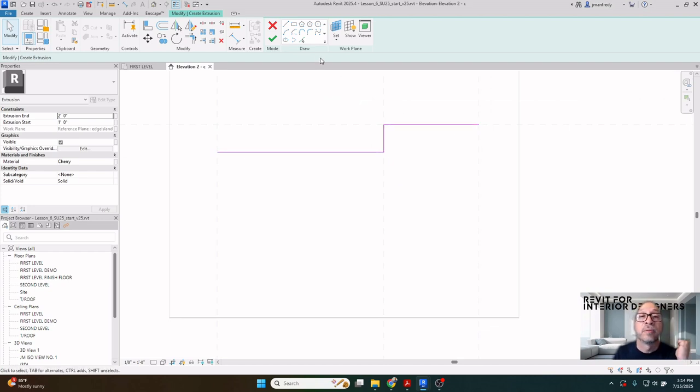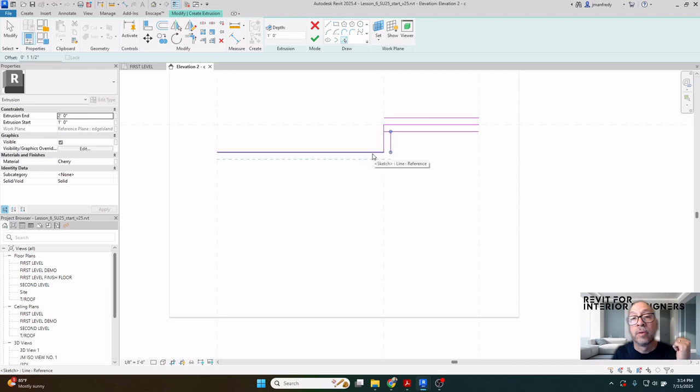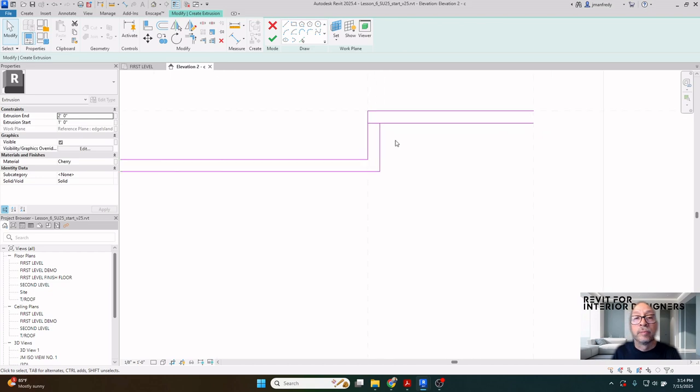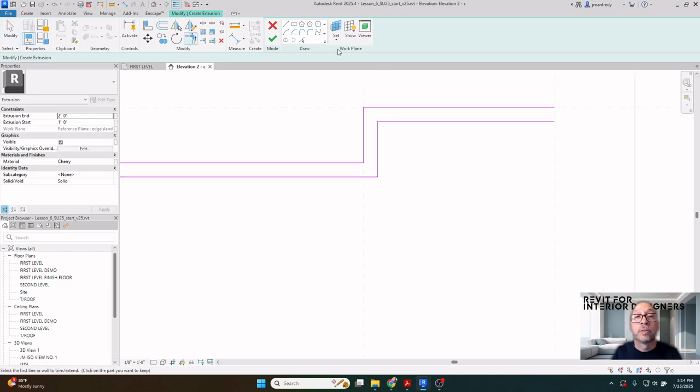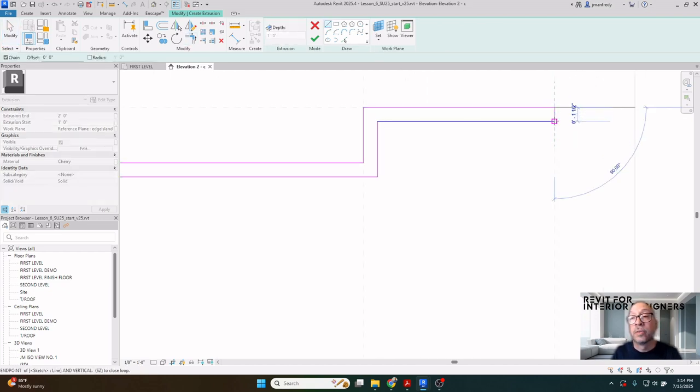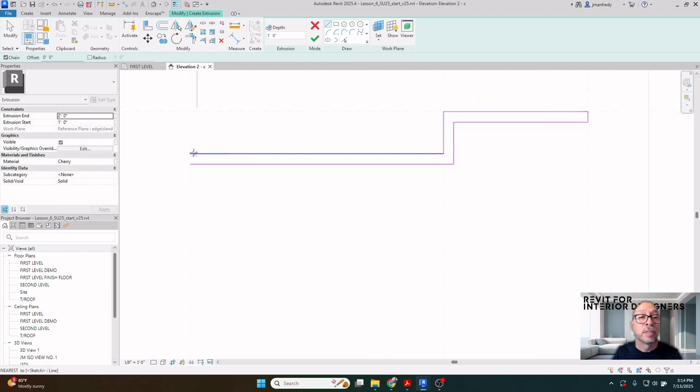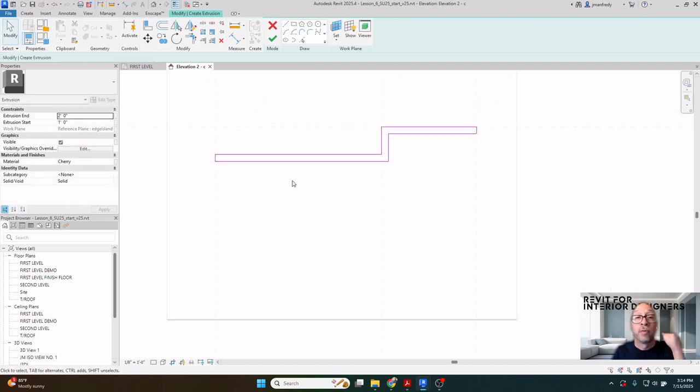It needs to have a thickness. So with the pick line command, I can pick something I've already drafted and copy it at a certain offset. This bar shows up here. I can type 1.5 inches, and then I can pick to select this object going down. This object here, go down here. Escape, and delete that one. I don't need that one. TR for trim the edges, and use this line command here to close the ends of this object. It has to be closed. It has to be perfectly drafted like this.